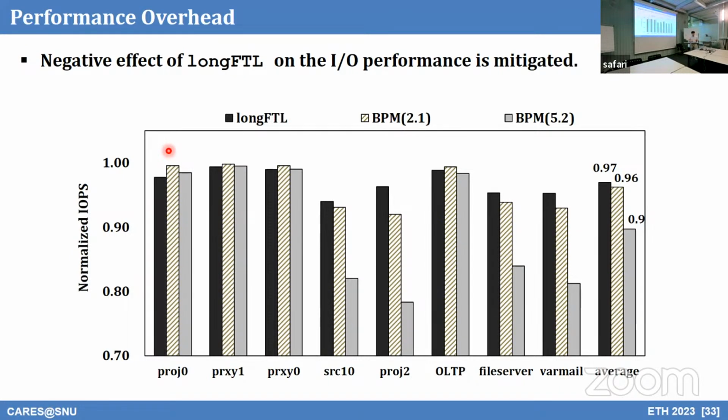We predetermine which word line is weakest and which is second weakest based on characterization. Within a block, it's a similar pattern; depending on where you locate it, the best, worst, and second worst, we can characterize it. And based on that information, we apply the weak word line ideas. Yeah. Okay.